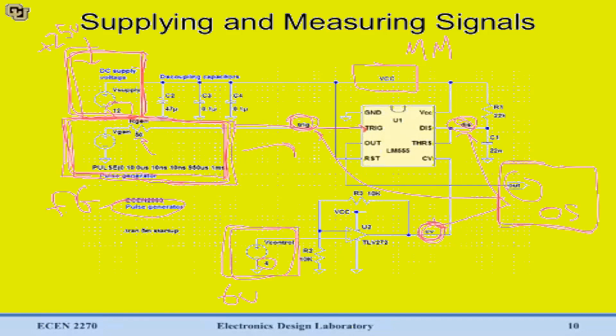So we're using our oscilloscope to measure outputs because we expect them to vary. We're using our multimeter to measure voltage rails because we expect them to be constant. We have our power supply generating both of these sources here, and our function generator set up for our input. So that's the basics of how you use this lab equipment. Most importantly, go into the lab, try and hit some buttons, try and figure out what does what. That's really the best way to learn this equipment.